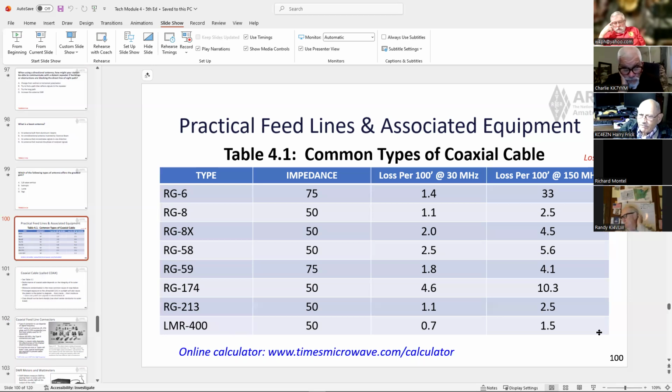And they make directional antennas invented by Mr. Beveridge, called a Beveridge antenna, and it can be laying on the ground, and there's a company that uses that RG6 as the feed element for that antenna. The longer it is, the more directive it is, but it is a receive-only antenna.